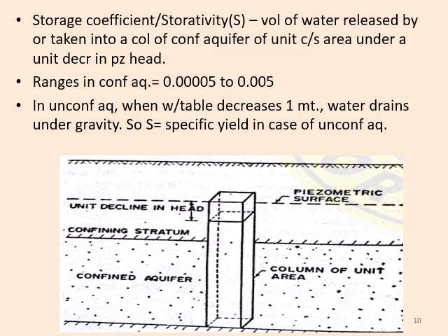Another term is known as storativity or storage coefficient. It is simply denoted by capital S. It is the volume of water which is released by or can be taken into a column of confined aquifer of unit cross-sectional area under a unit decrease in piezometric head.